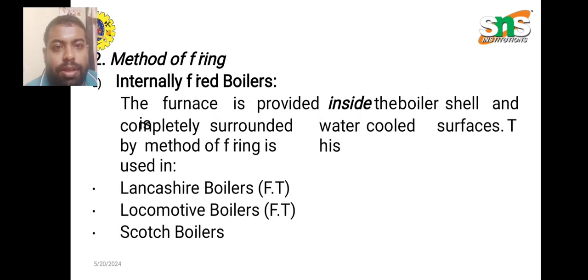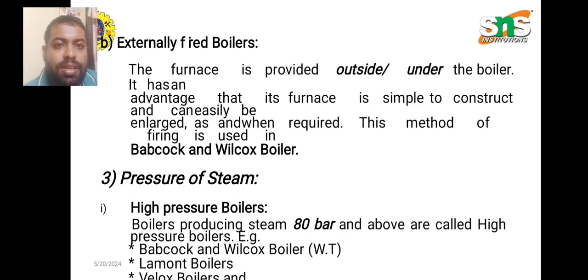Method of firing. Internally fired boilers: the furnace is provided inside the boiler shell and it is completely surrounded by water cooled surfaces. This method of firing is used in Lancashire boilers, locomotive boilers, and Scotch boilers. Externally fired boilers: the furnace is provided outside or under the boiler. It has the advantage that its furnace is simple to construct and can easily be enlarged as and when required. This method of firing is used in the Babcock and Wilcox boiler.